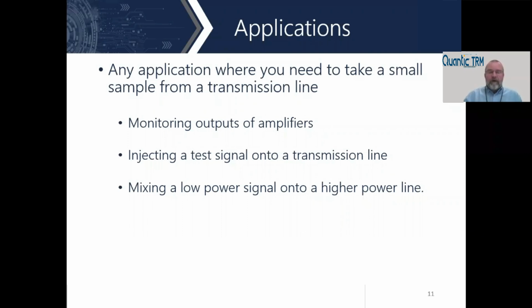Basically, every amplifier needs to understand how much power is being broadcast out. So very often at the output of an amplifier, you will see a directional coupler, both to sample the forward direction, as well as how much energy is being reflected back. In those cases, you will very often have different coupling values in a single dual directional coupler.